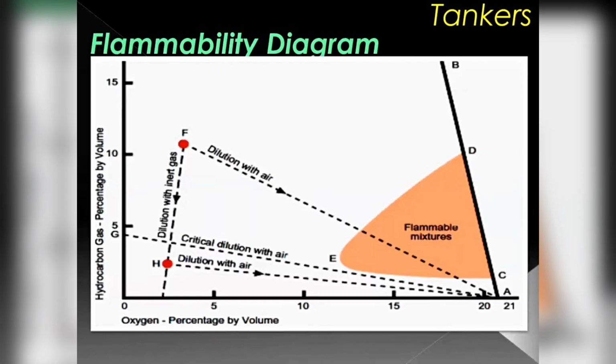Third, hot work procedure has become very stringent. Nobody is appreciating doing hot work on ships, on tankers. They are forcing people on board to come out with some cold work and solve the problem. Unless it's absolutely necessary, hot work is not so common in tankers nowadays. Am I right? Yes, sir. And nobody is appreciating carrying out the hot work.